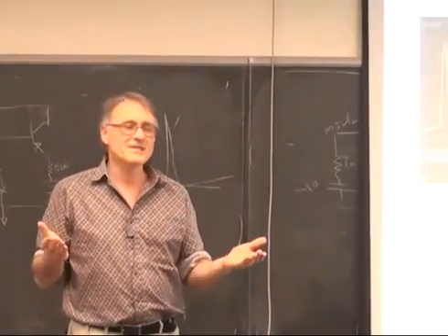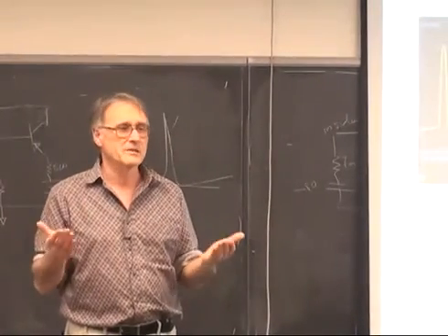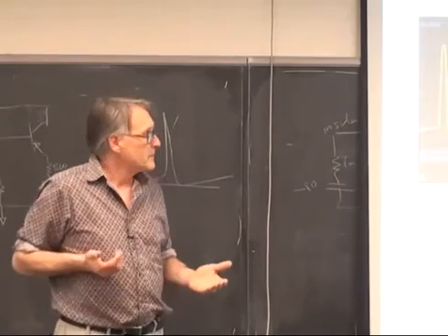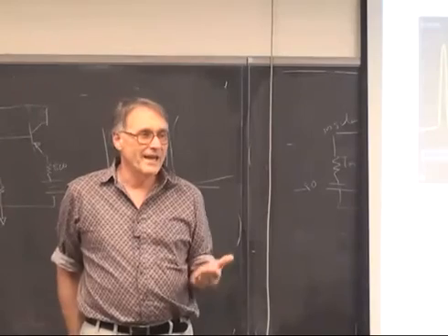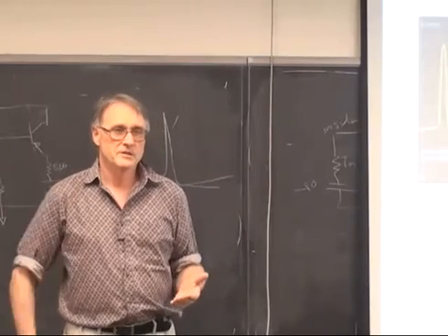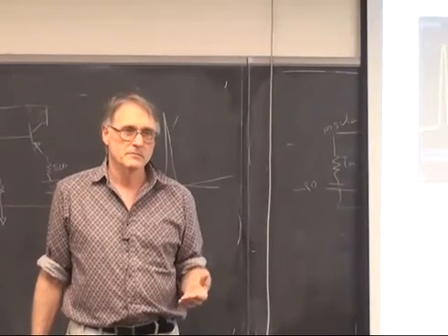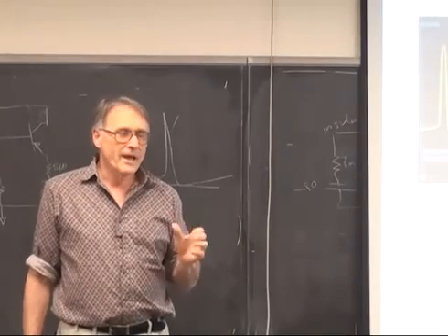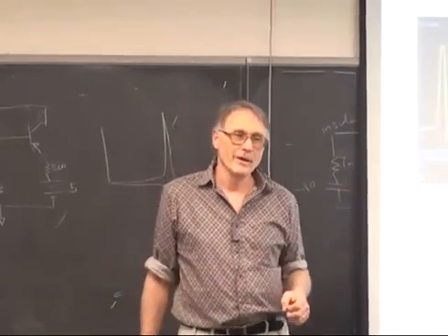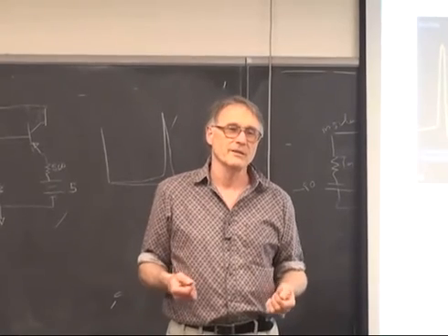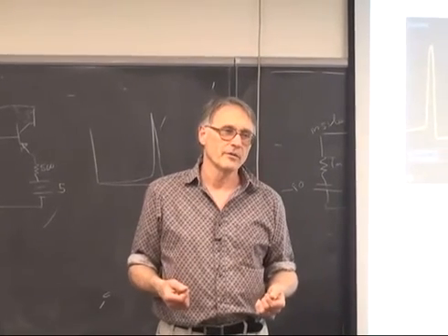The ratio of the fastest time constant to the slowest time constant is big. And most differential equation solvers tend to fail under those conditions, and SPICE is no exception. So you can't necessarily take these values, plug them into a whiteboard with real transistors, and expect it to work. You have to fiddle with it a little bit.